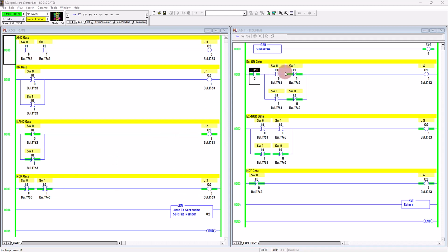This one is series, which is AND, which is multiply. So 0 times 1, 0. As for this one, 0 times 1, 0. Then this one and this one is parallel, which is OR. OR means plus. So 0 plus 0, here 0. As for this one, 0 times 0 is equal to 0. This one in series, so 1 times 1 is 1. So both parallel, so parallel means OR means plus. So 0 plus 1, the output is 1, is energized here.